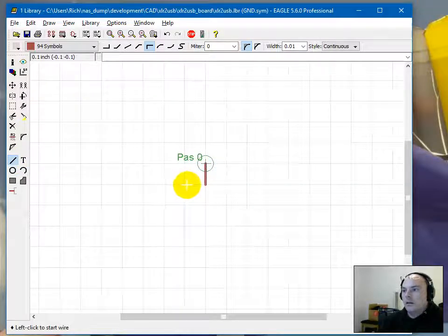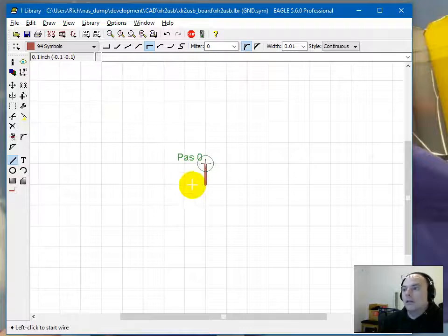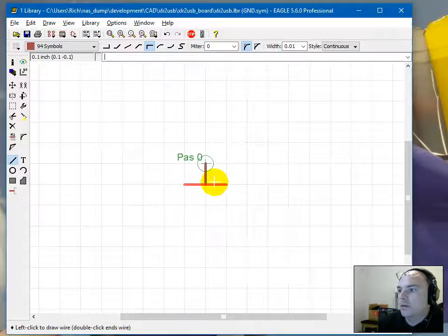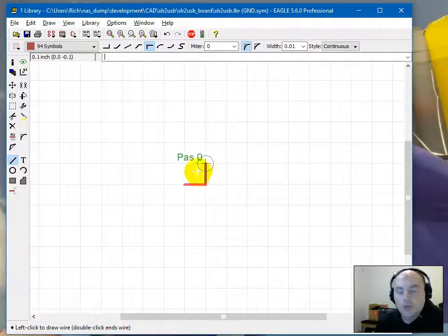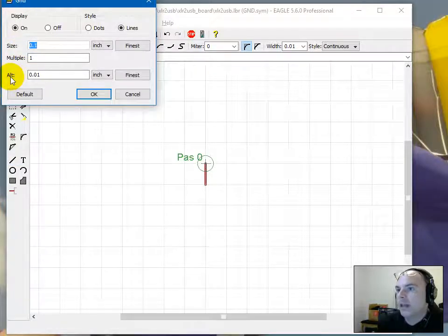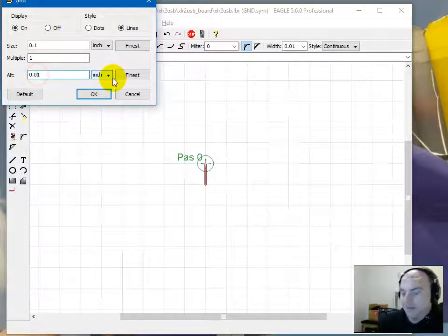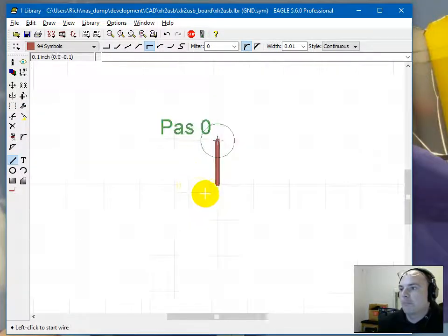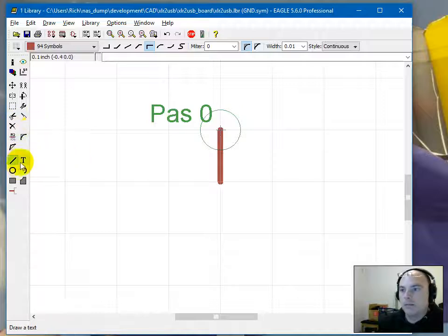That means this is a good example to show you what you can do with the grid. This looks terrible. It's not enough grid for me. Grid has an alternate mode. This is the granularity you use when you hold down the Alt key. That's a little too small for me, so I'm going to do 0.025. Right, so 4 steps per. Cool. It gives me a midpoint.